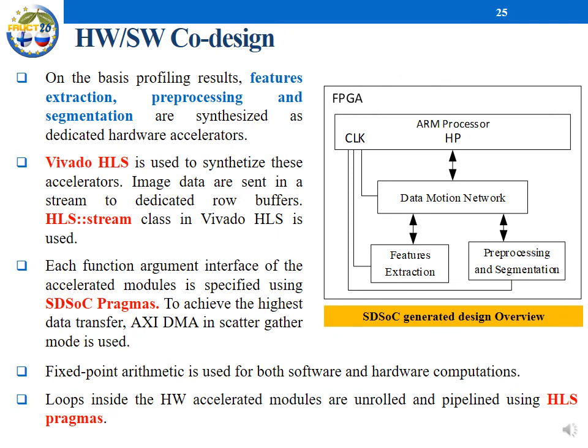In hardware-software co-design, we have the following points. On the basis of the profiling result, feature extraction, preprocessing, and segmentation are synthesized as dedicated hardware accelerators. Vivado HLS is used to synthesize these accelerators. Image data are sent in a stream to a dedicated raw buffer, and the HLS stream class in Vivado HLS is used.